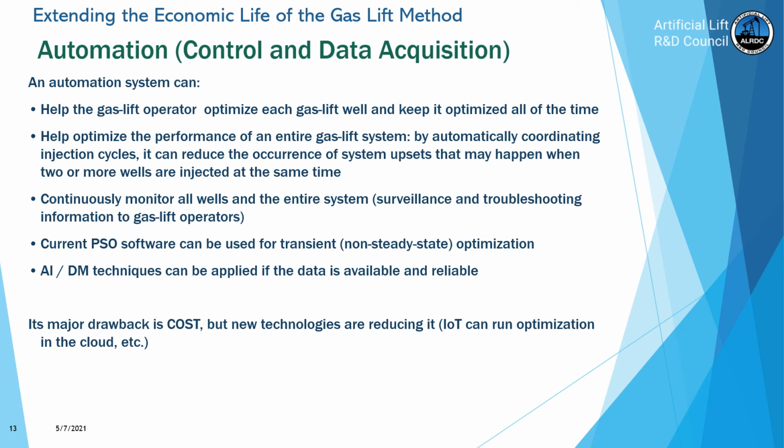And at that time, when the intermittent almost closes, the annulus pressure should decrease, because the volume of the gas flow rate through the operating valve is very high now compared to what we are allowing to enter into the annulus. So eventually the pilot valve will close. But once the pilot valve closes, the pressure in the annulus increases in the same way that it will increase in choke control intermittent lift. And eventually it will reach a pressure just below the opening pressure of the downhole valve.